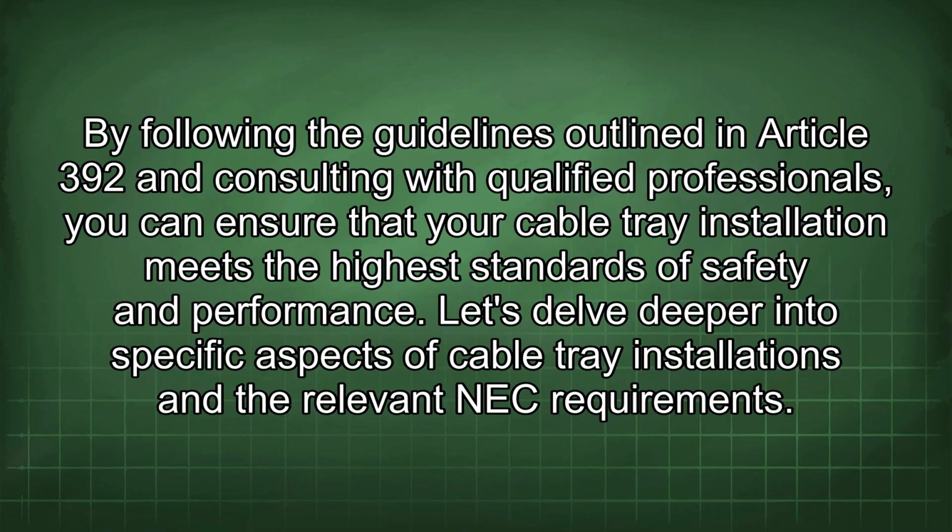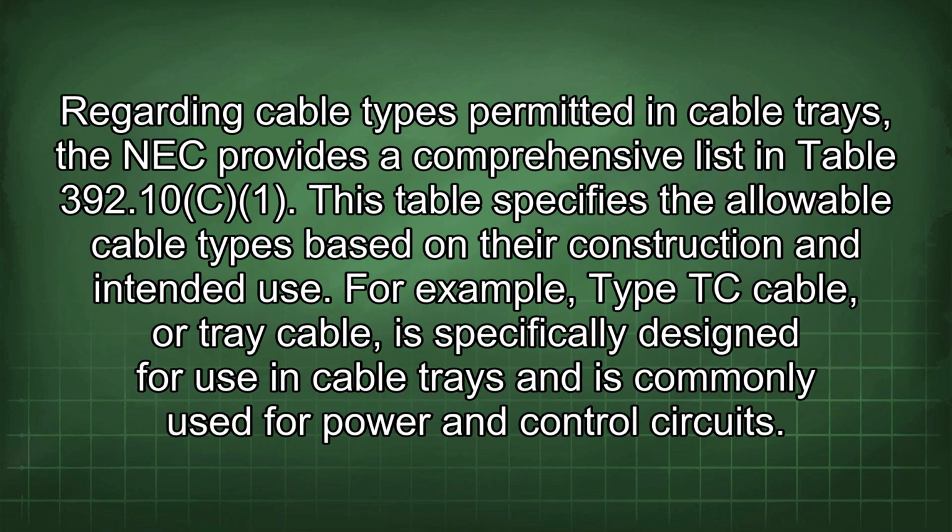Let's delve deeper into specific aspects of cable tray installations and the relevant NEC requirements. Regarding cable types permitted in cable trays, the NEC provides a comprehensive list in Table 392.10(A). This table specifies the allowable cable types based on their construction and intended use. For example, Type TC cable, or tray cable, is specifically designed for use in cable trays and is commonly used for power and control circuits.